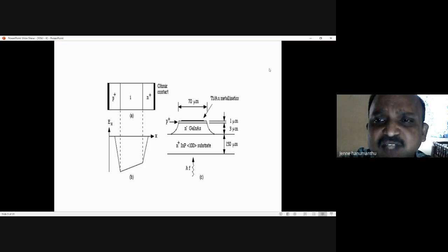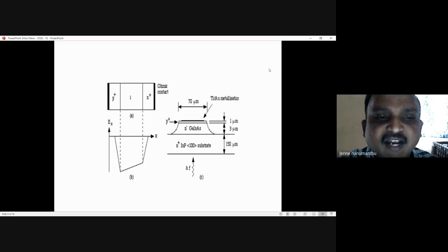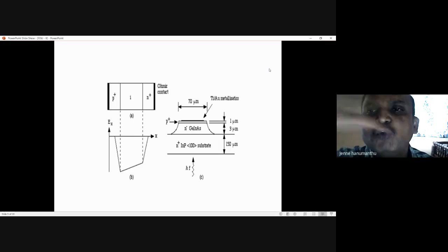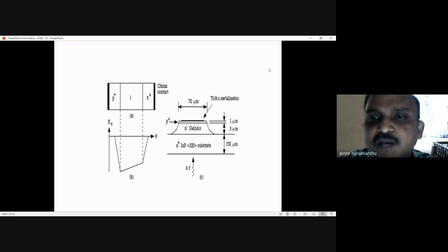You can see it in nanoamps or milliamps. So the PIN diode simply converts the light signals into electrical signals in the form of current. Or if you want voltage, you connect a voltmeter across a resistor, and you may get nanovolts or millivolts. That is your wish.